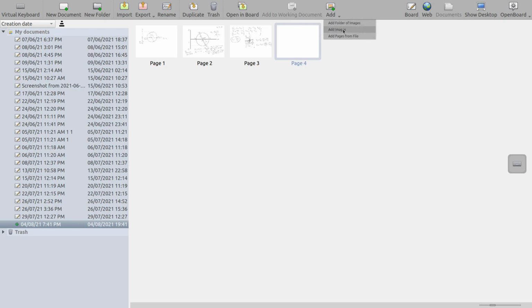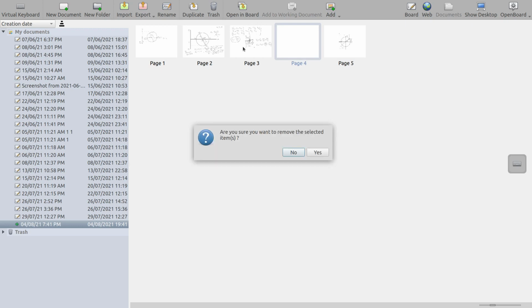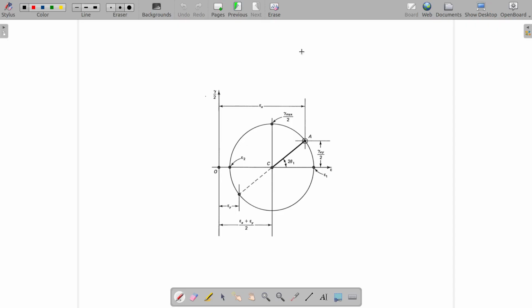When we draw the Mohr circle for strain, it's going to be very similar to that of stress, but the only difference here is that for the shear component we are using a half, and we have to use that half because of our definition. Other than that, everything else will be the same.